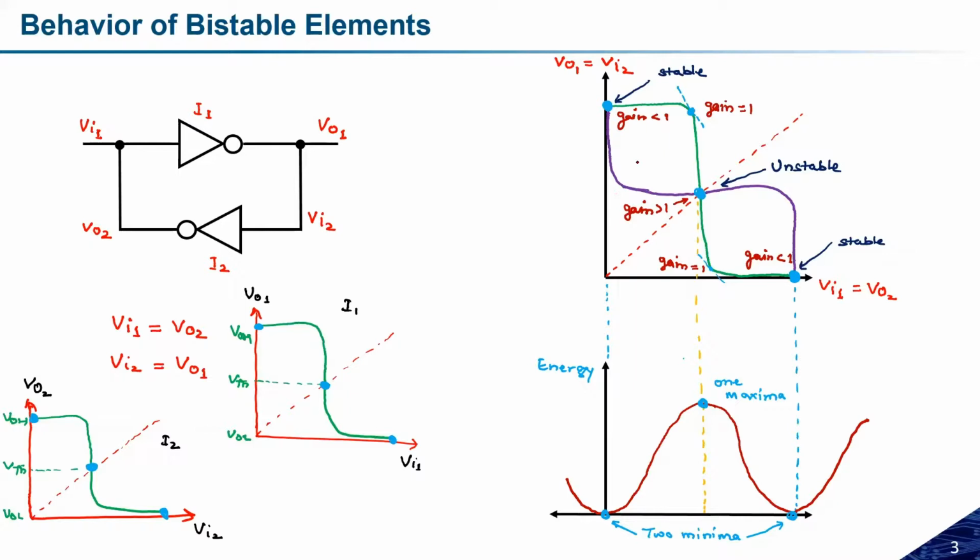Let me explain from this circuit. If you see this circuit, at this particular point, both the transistors in inverter 1 are in the saturation region. And if both the transistors are in the saturation region, the output we will observe is equal to the threshold voltage of the circuit. This is not the threshold voltage of the transistor. You should remember it, right?